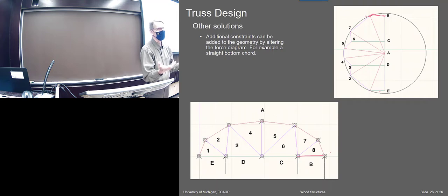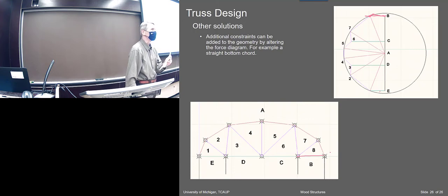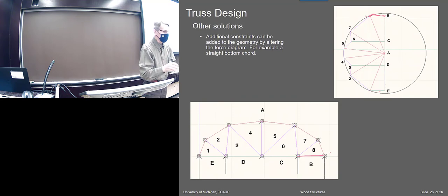Same as a steel manual. They're probably trying to copy the steel manual. Well, the tables aren't quite as wonderful as the steel manual tables, but okay. You can pretty quickly pick a member, and at least it calculates CP for you. So these are for 4x dimension lumber. Looks like everything's Doug fir. I guess that's what we're using, I hope. Yeah, Doug fir number 2. So these are all for Doug fir number 2.